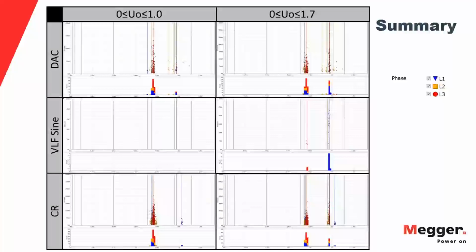Yes, but you'll probably need a support capacitor. On my diagram, wherever that was in the presentation, you need a certain minimum amount of capacitance in the system, whether that comes from the cable or a support capacitor, it's all the same. And yes, cables less than 200 meters can be tested, depending on the equipment. Some of the equipment has the support capacitor built in, some of it doesn't, but you may need that.